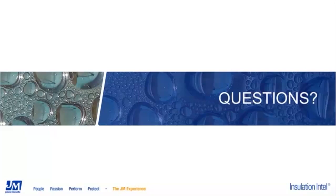Sure, thanks, Meredith. The thermal conductivity values that we report and that are contained in the ASTM documents for PIR and Phenolic, those are already aged values by rule. There's various laws about this as well. So we're very conservative in both the aging of samples before testing, as well as we report conservative values.